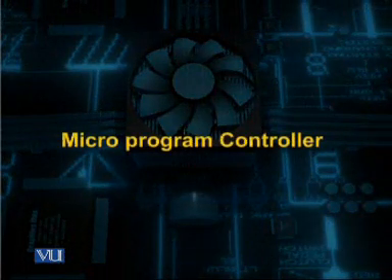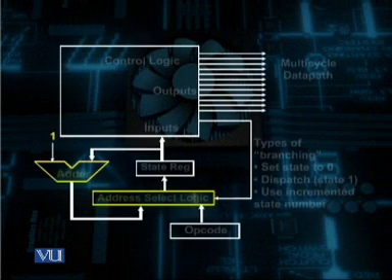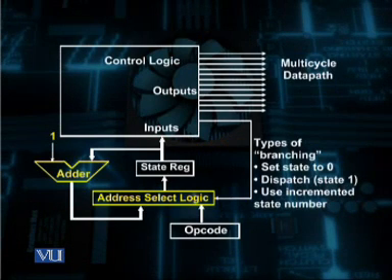As you can see from this block diagram, whenever we know the instruction code, we can identify this by loading the starting address of a particular instruction into the program counter, and this program counter then gives us all the micro operations which are to be performed, and they are already stored in the ROM which is used with this circuit.